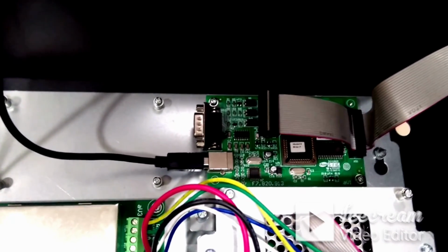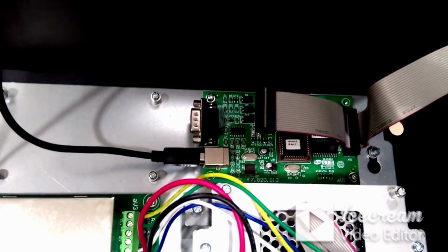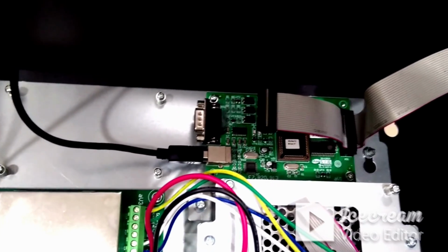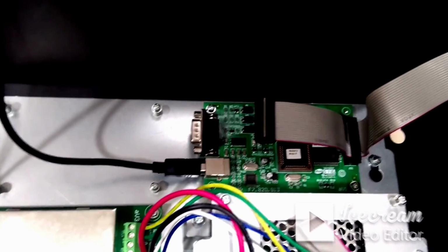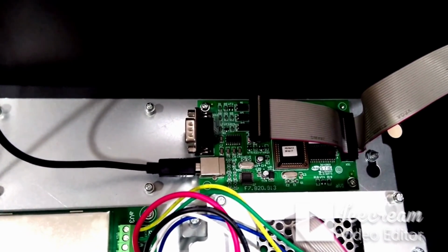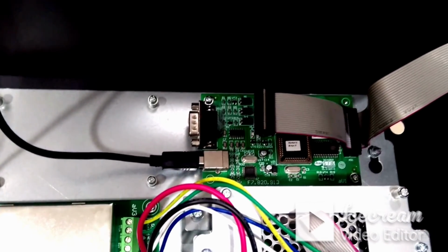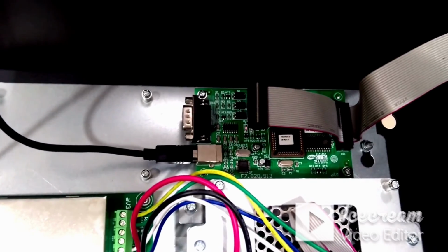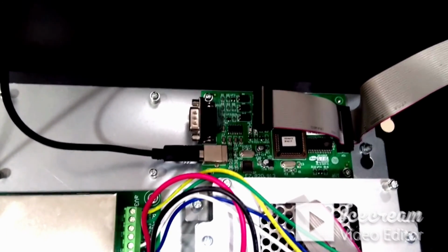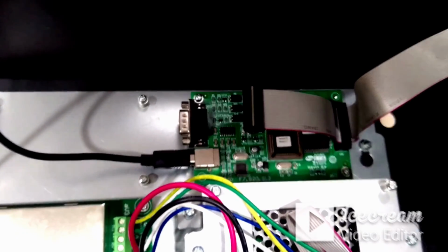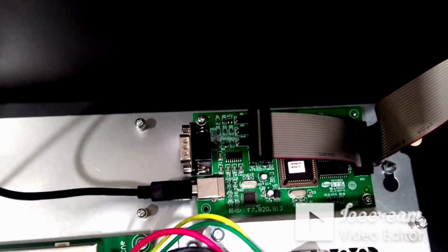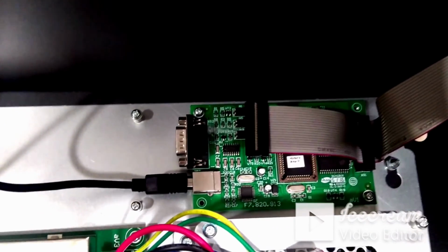And again, once you commission the panel completely and remove this card from the panel, we need to do the auto learn again so that the card will be deleted from the panel memory. If not, it will show an error on the panel. So whenever we use this card, we need to register it, and whenever we complete the commissioning and remove the card from the panel, we need to do the auto learn again, so that this card will be deleted from the panel memory.